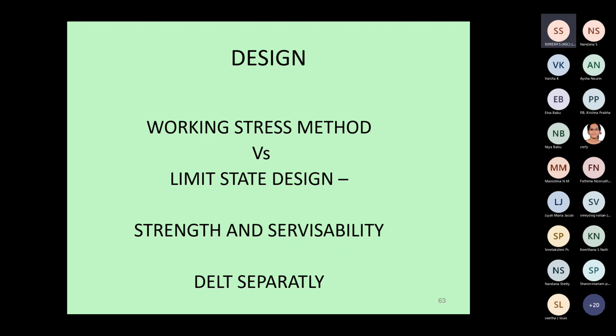We take only 95% passing value, then most 95% of the samples will fall above M25, meaning it may be M26, 27, 30, 35, like that higher value. 5% will be lower. And then we apply a factor of safety on this FCK value and say this is the allowable stress in the material or working stress in the material, concrete.